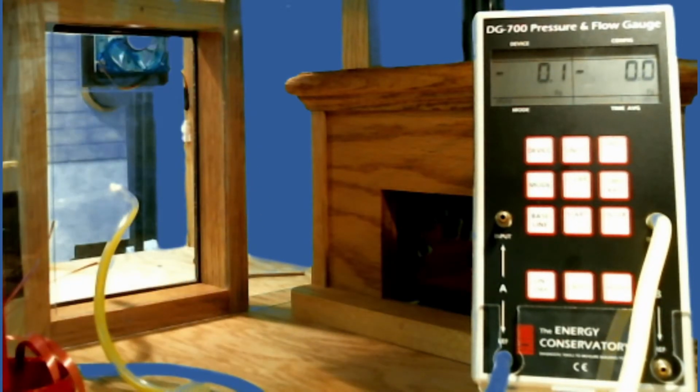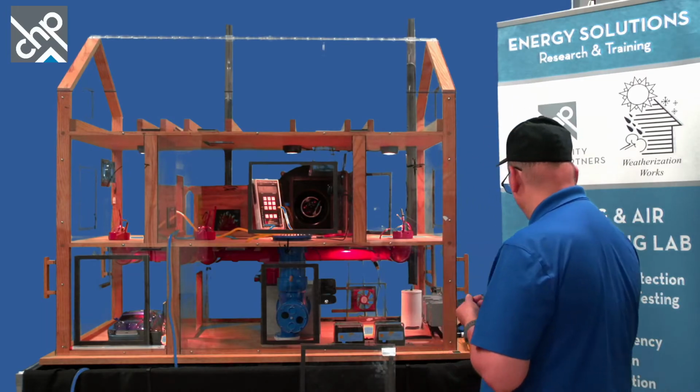You can see it. If you're at a house, what you're going to do is slide that hose under the door, usually 2 or 3 feet. You want to slide that under the door a good 2 or 3 feet, and then shut the door on that hose, and then you would take your reading. You would do each room like that. So we want to do that for this room.